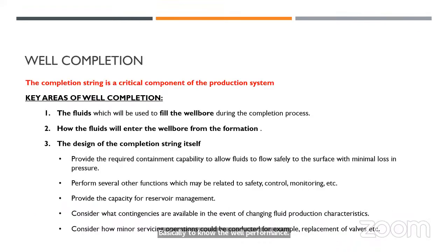Okay, the concept of well completion is the process in which we install the production tubing that will control how the fluids will come up to the surface. So in order to do a well completion efficiently, we need to understand the reservoir fluids. We need to understand how the fluids will enter the well bore from the formation. This means whether our reservoir is very tight or the permeability is good and the productivity of the reservoir itself is good.